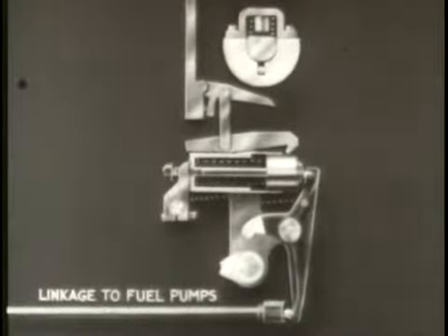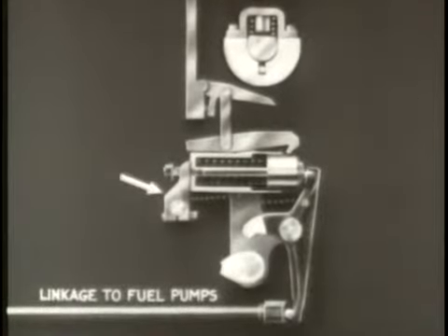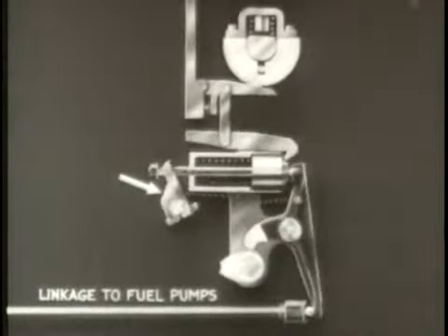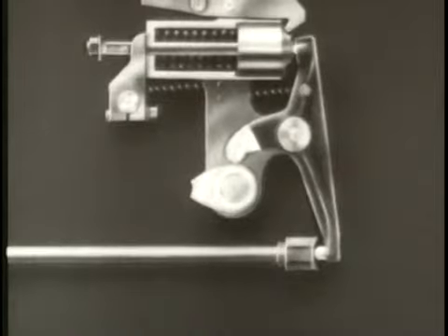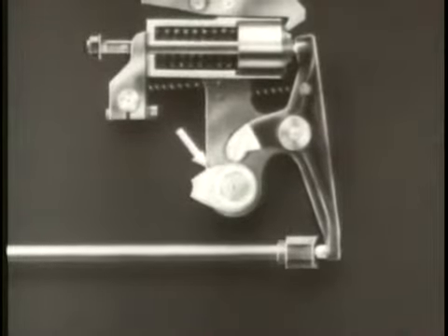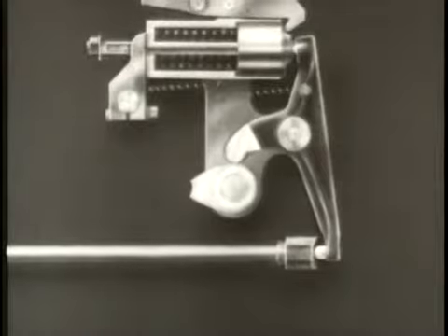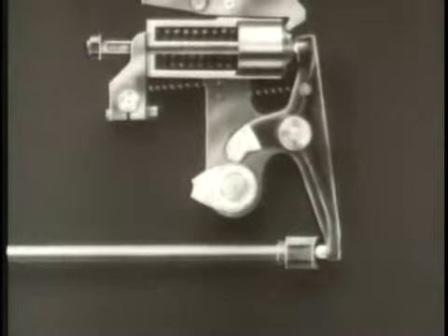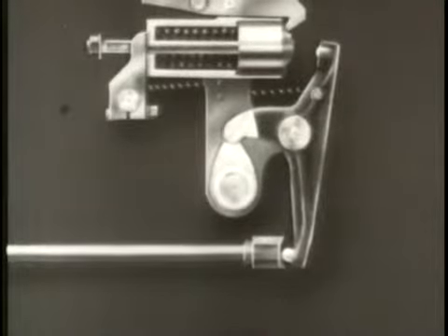Before the engine can be started again, the latch and the fuel pump must be reset. This is done by this reset arm, which is mounted on the reset lever shaft. The fuel cutout cam, mounted on the control shaft of the engine, is used when stopping the engine by hand. When the starting lever of the engine is moved to the stop position, the cam turns the cutout lever, shutting off the fuel pumps.